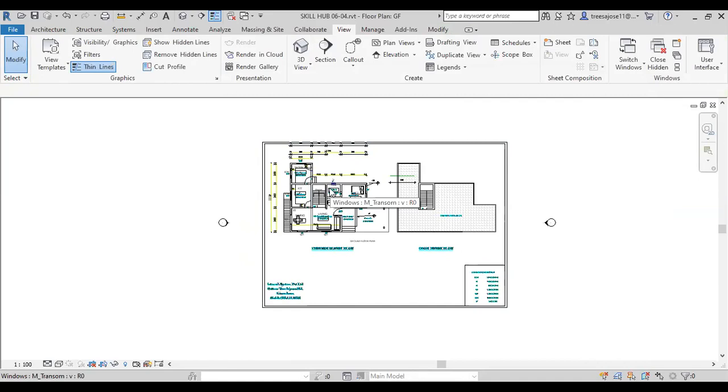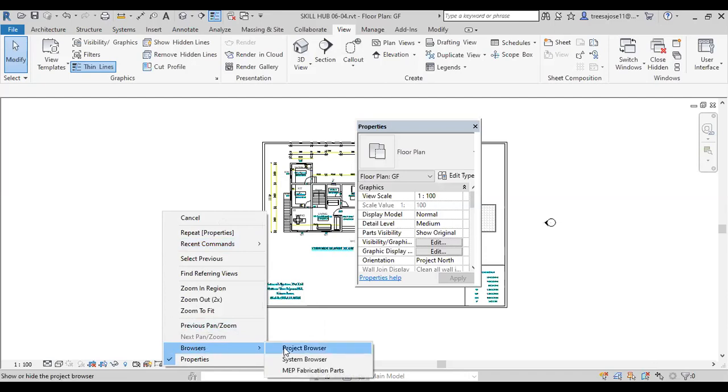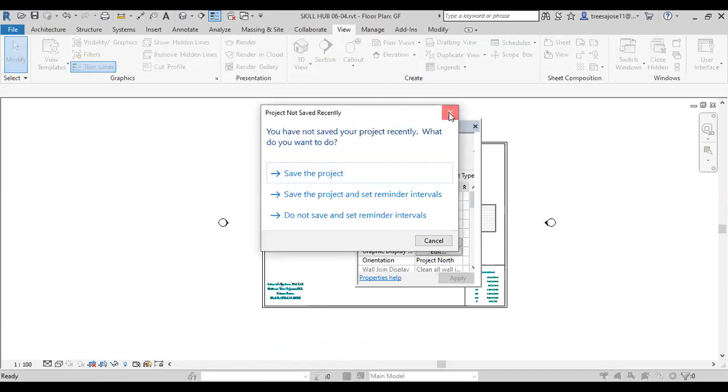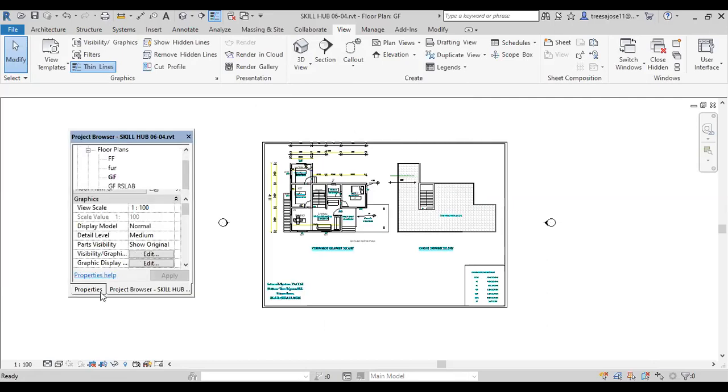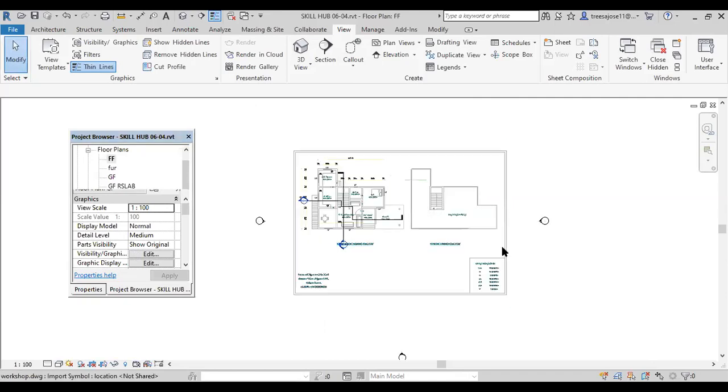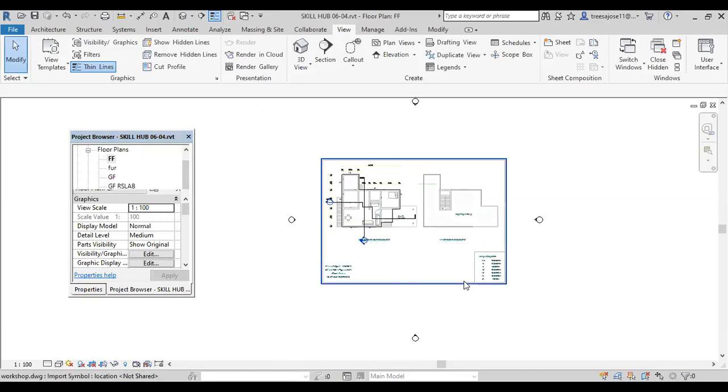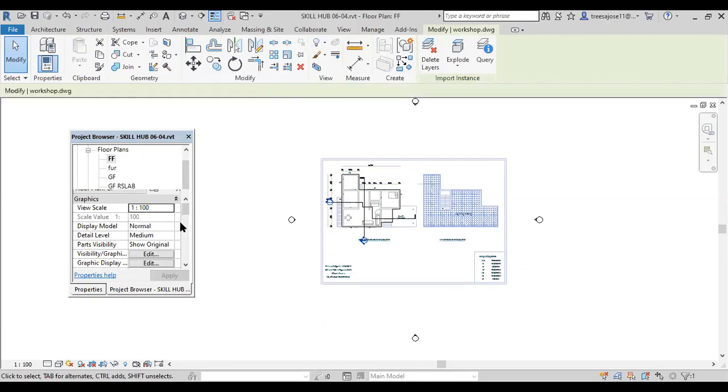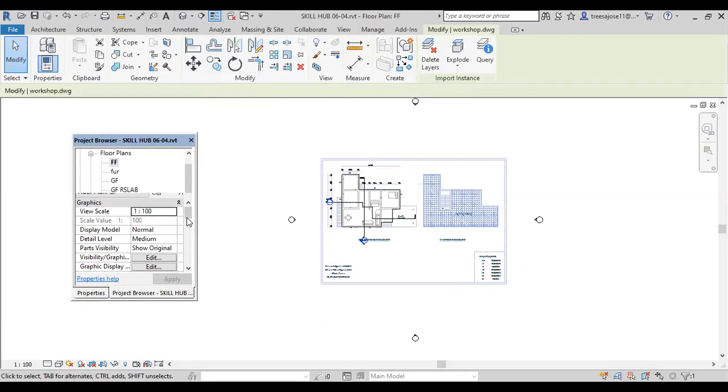In the case of a typical section, we can copy to clipboard and place it. But in the case where the structures are not typical, we have the second floor plan with its own layout. For example, I activate the first floor plan. You can select this image, which may come under the ground floor, and change that into first floor.